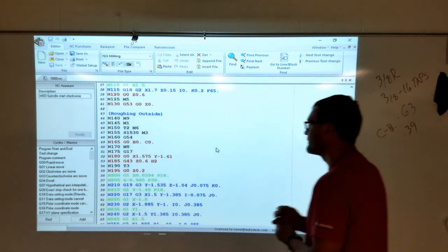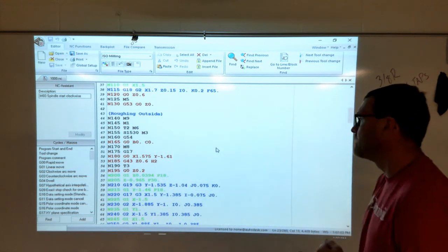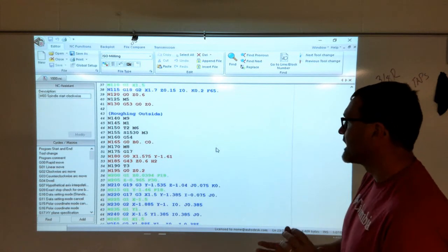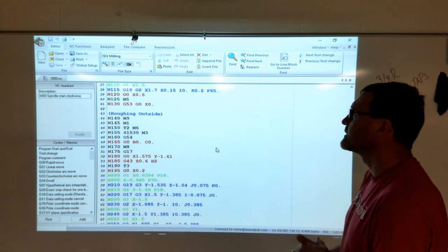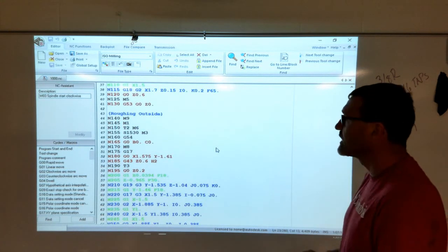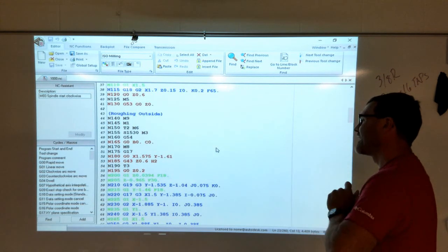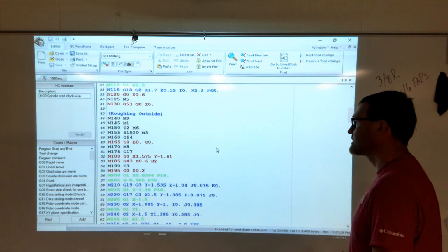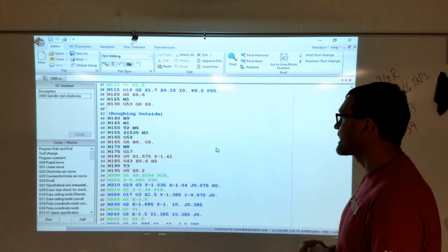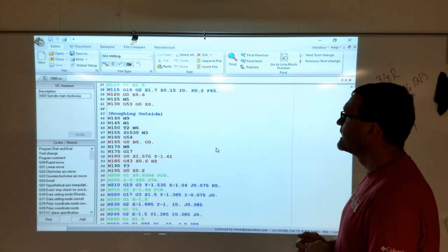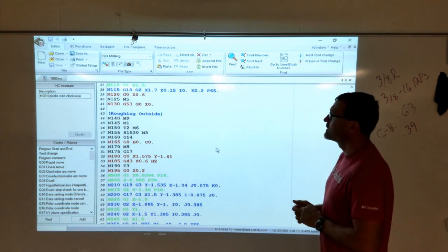You're also going to see some different feed rates for different things. That's in an effort to keep it moving as fast as it can to keep as much contact in there as you can. They're not bad things, but they're just not always going to be things that everybody's used to, especially if you've done a lot of hand programming before. If you come out of the operator class, you don't know what that means anyway, so it's not going to really bother you. But if you've already been programming, if you've already taken 109 and you're backtracking into CAM, then some of those things are going to be a little bit more difficult for you.